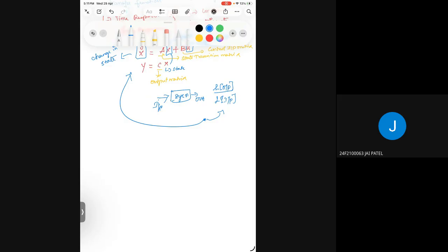But when compared to transfer function, state space is more flexible in that you can use it for higher order systems, where doing that with the transfer function is difficult because a transfer function represents the relation between one input and one output. If you want to represent two inputs, for example, I have input 1, input 2 for a system, so that I'm getting output 1 and output 2, we don't know the relation between these with the transfer function.